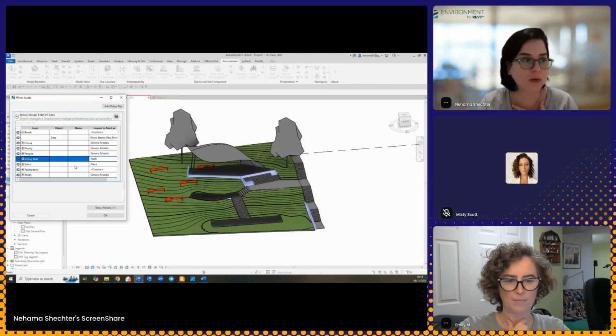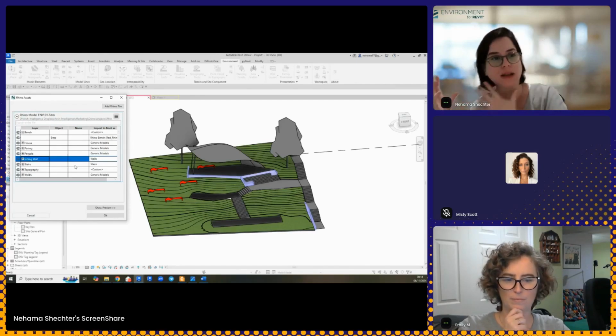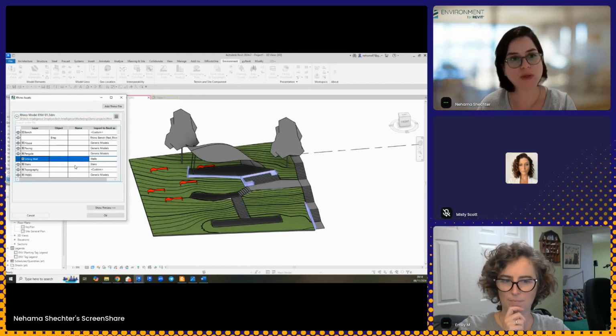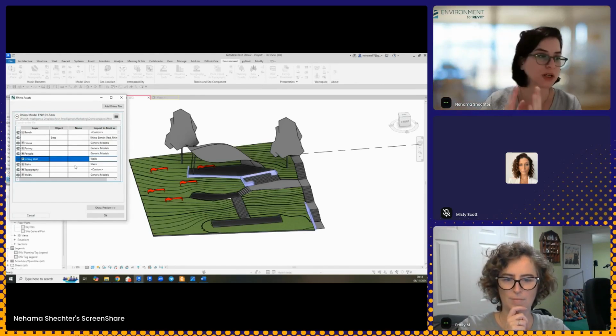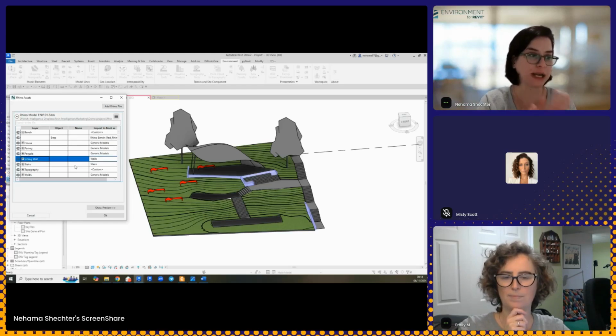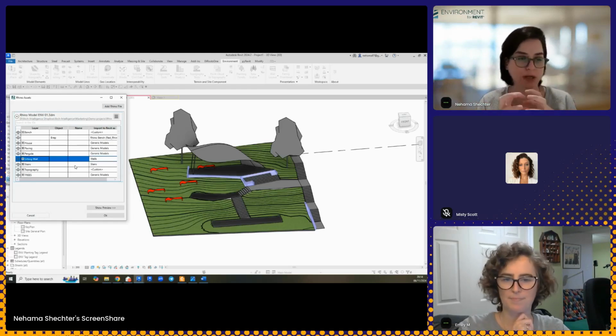If you create a total mess in your Rhino layers, it will be more difficult to work with that in Revit later, because Revit works according to categories rather than layers. Layers are more free form, where you can take every object and put it in every layer, but categories are more strict. So my suggestion is to think about your layers as categories, right?